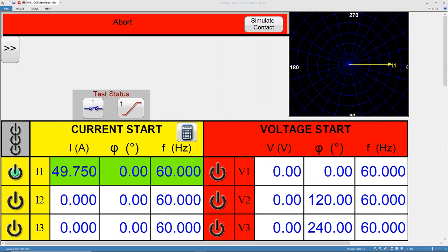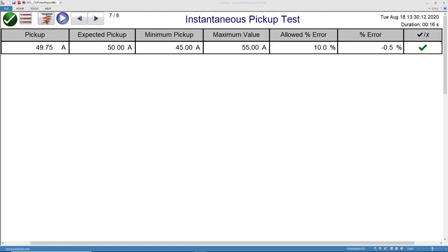Another thing I like to always say too is when we're doing any type of test, we want to make sure that our ramp or pulse duration starts before the tolerance. So if you're looking for a 10% tolerance in your relay settings or in your test, then we want to make sure that we start our ramp before that. So it could be 15% or just somewhere outside of that tolerance band, because you want to make sure that you're actually getting proper test on it and you're covering your basis with your tolerance levels.